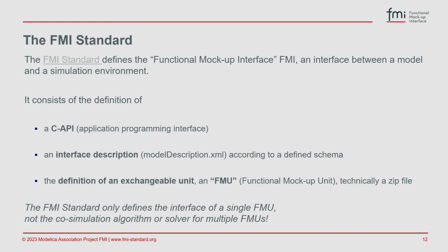One important takeaway is that the FMI interface defines only the interface to one FMU. Even though normally you couple it with something, you simulate multiple FMUs, you co-simulate them, but the algorithms about the co-simulation, they are not defined by the FMI standard. There is freedom, so you can select the suitable algorithm. The only thing the FMI interface defines is the interface.